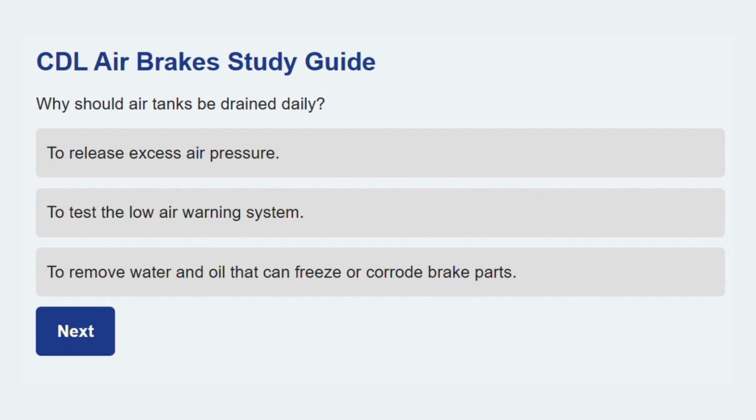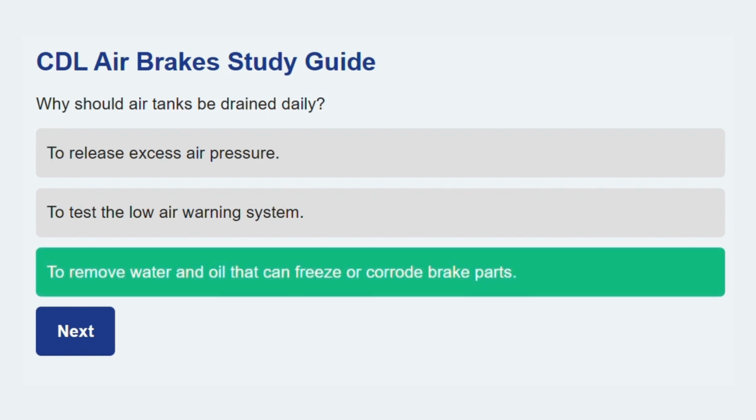Why should air tanks be drained daily? To remove water and oil that can freeze or corrode brake parts. Moisture in the air system can freeze in cold weather, causing brake failure, and oil can damage rubber components.